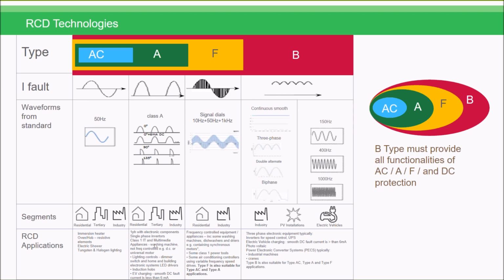So we look at some of the newer types that are mentioned in the 18th edition. So we've got F-type there, and the F-type RCD achieves tripping as for type A, and in addition for composite residual currents, whether they're suddenly applied or slowly rising, intended for circuits supplied between phase and neutral or phase and earth middle conductor. So for residual pulsating direct currents superimposed on smooth direct currents.